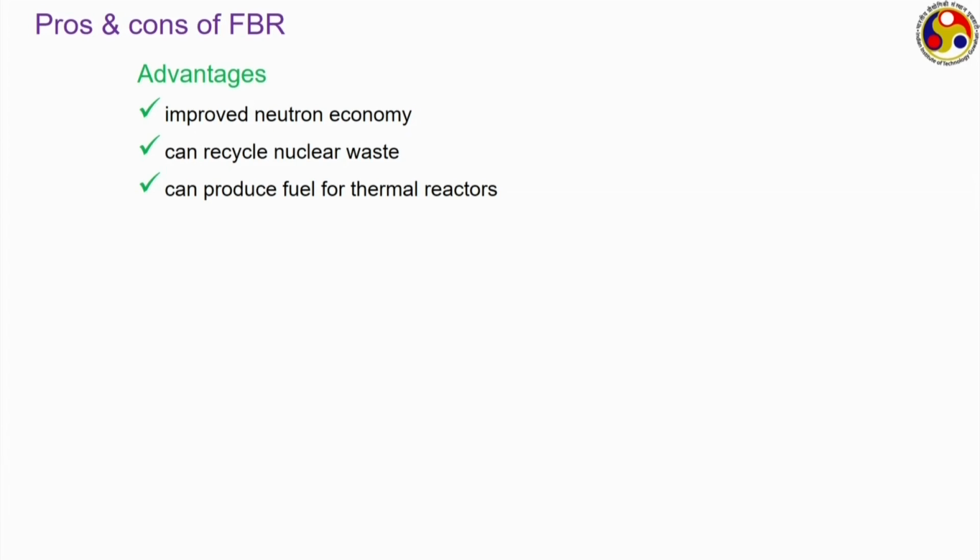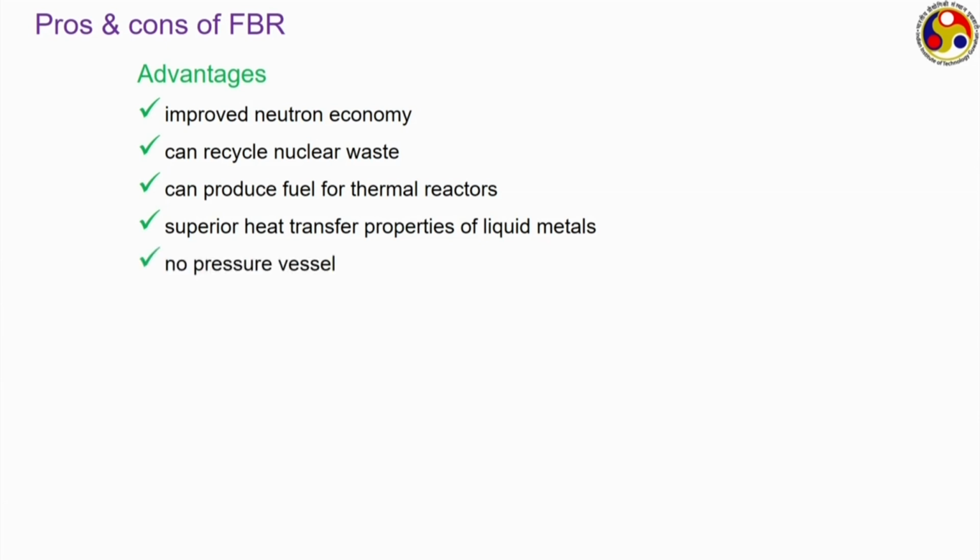Now, when doubling time has been attained, that reactor or excess waste fuels can be taken out, can be reprocessed slightly. Those waste products can be taken out and can be processed slightly, and in course of doubling time it will produce the same number of new fuels as it originally had. So, that new fuel can be used to start a new thermal reactor. Then liquid metal has much better heat transfer characteristics compared to water, which is advantageous. No pressure vessel, that is another big advantage also.